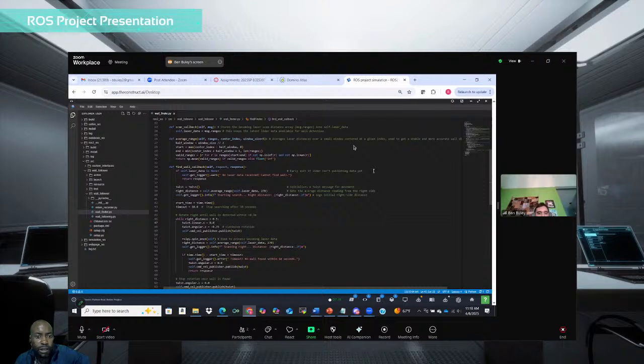Next, so right here. I'm sorry, are you saying that you made the amount of ranges data that you have to process per instance slightly smaller for you to be able to detect the wall? Yes, when it had an increased range, I found that it would enter a kind of continuous loop. It would have a hard time detecting the wall, and at points it would just start spinning in circles, trying to detect where it was. Okay, so when you made it finer by taking a little at a time, that makes sense.